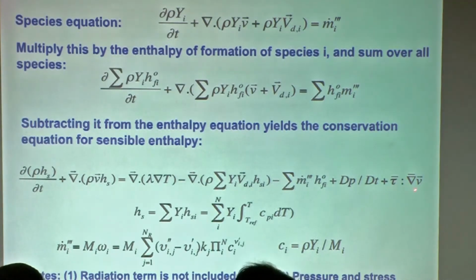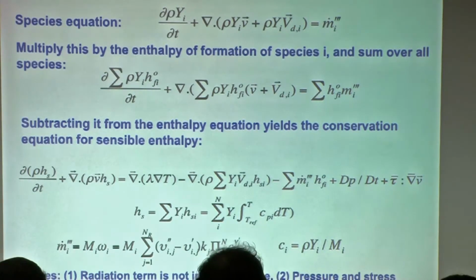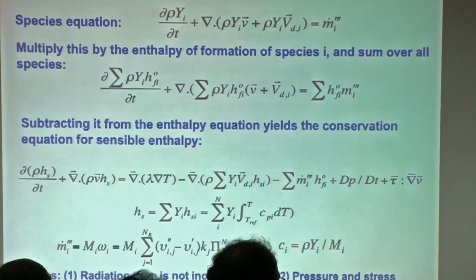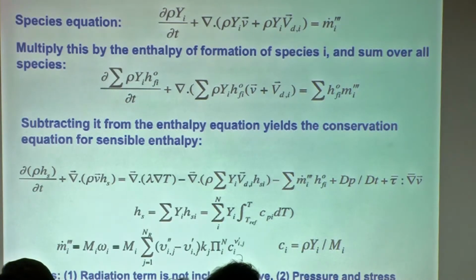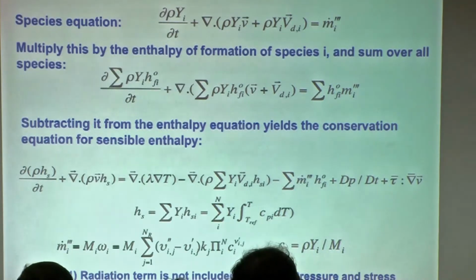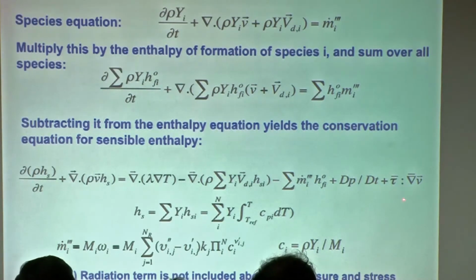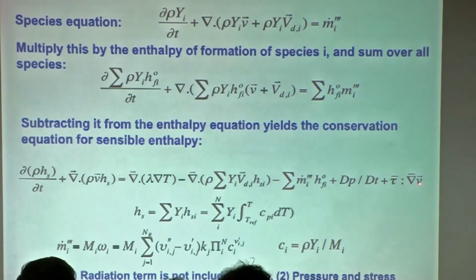This term, when you write it out, because what is tau? Those are the nine stress components. If you write all those out, this term is always positive and represents the viscous dissipation of energy. Like in aerospace, when the space shuttle enters the atmosphere, it generates a tremendous amount of heat, right? That's mainly this term, the viscous drag, we call it. So this is important only when you have high speed flows, or very low speed lubricating flows with high gradients.